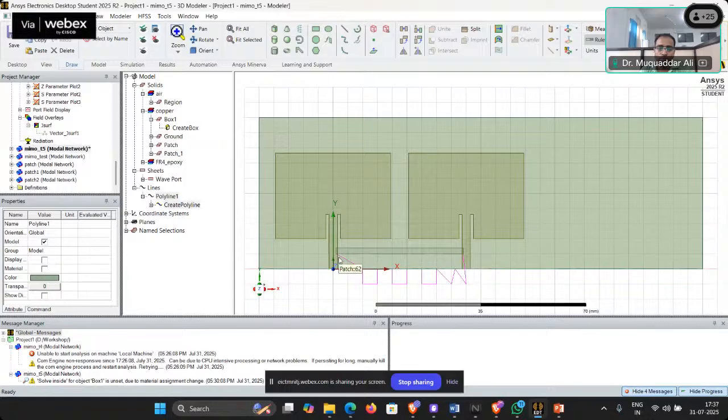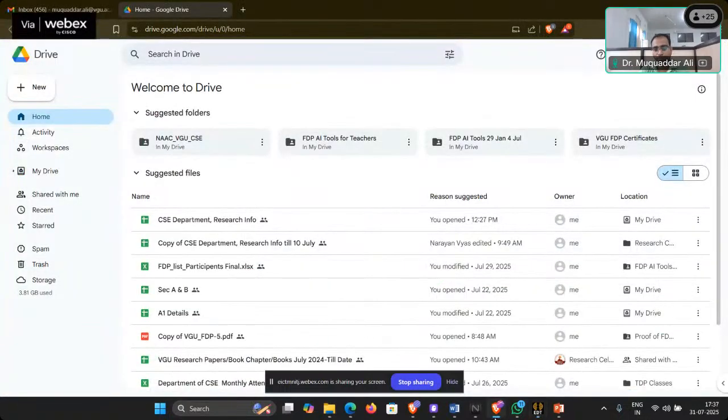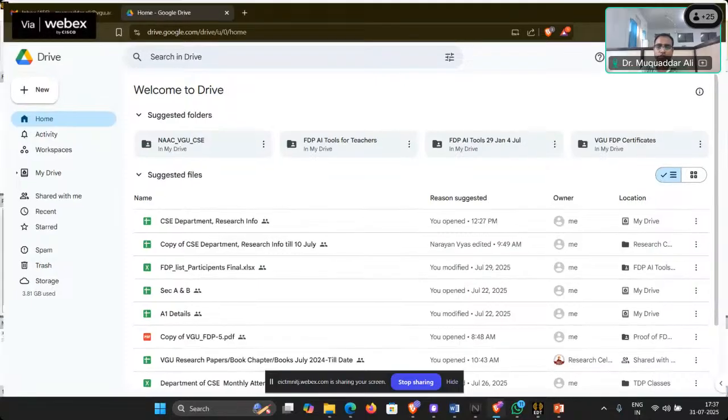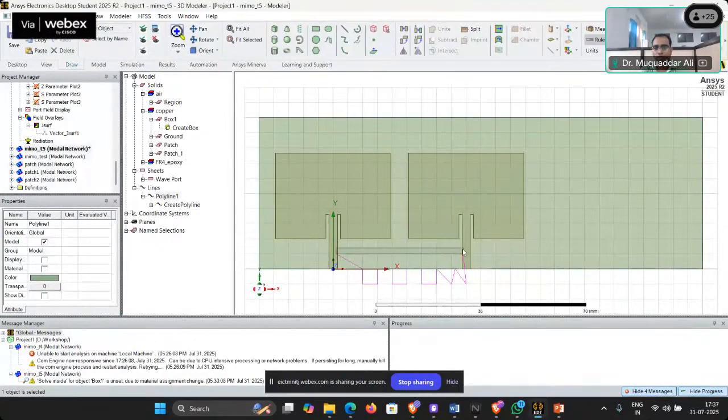So in that we have to make sure that this line is called a neutralization line. This neutralization line is sampling only the sample. If our S21 was minus 10 dB, that means 10% power was coupled. So this neutralization line should only take 10% power from here and it reaches here. Okay. So what are the disadvantages of this technique? In this technique, we are extracting a signal that should have been transmitted. Okay. So basically, we are reducing the efficiency.